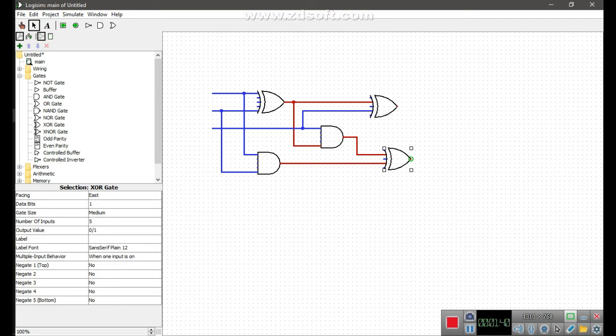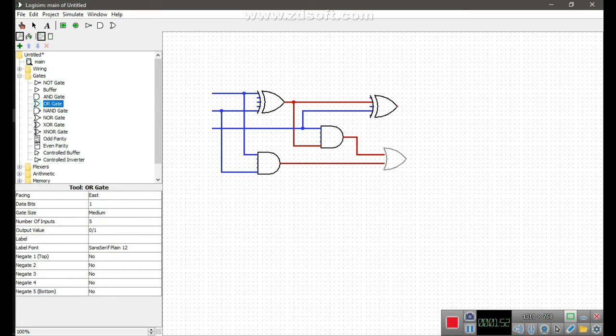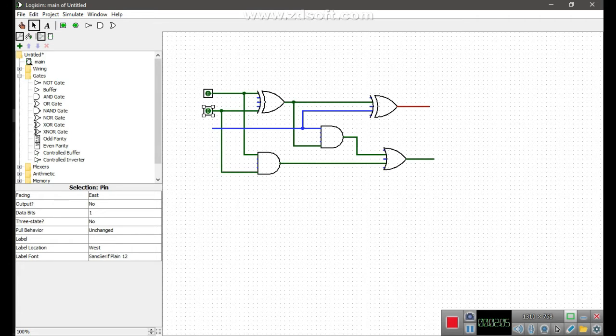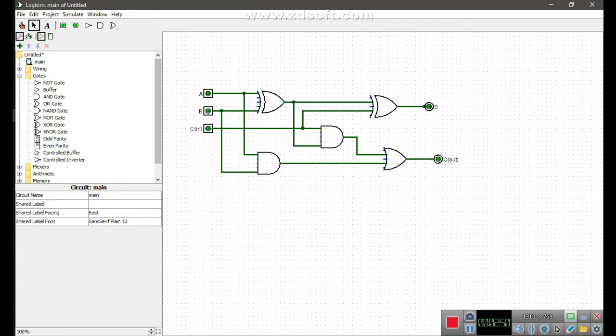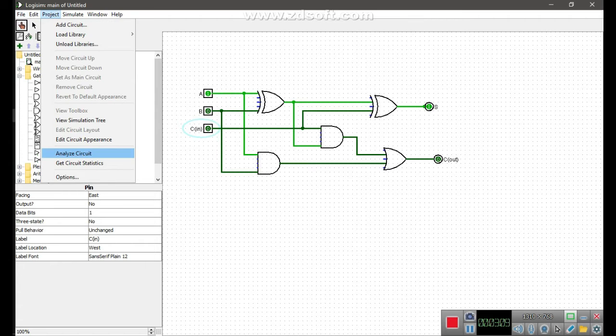The first two inputs are A and B, and the third input is a carry, C in. When the full adder logic is designed, you string eight of them together to create an 8-bit wide adder, and cascade the carry bit from one adder to the next. Here also you can see the truth table of this full adder.